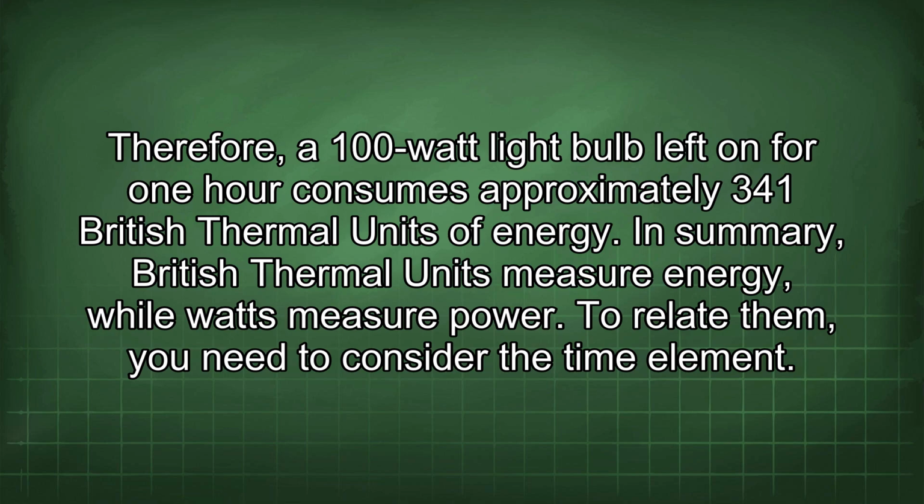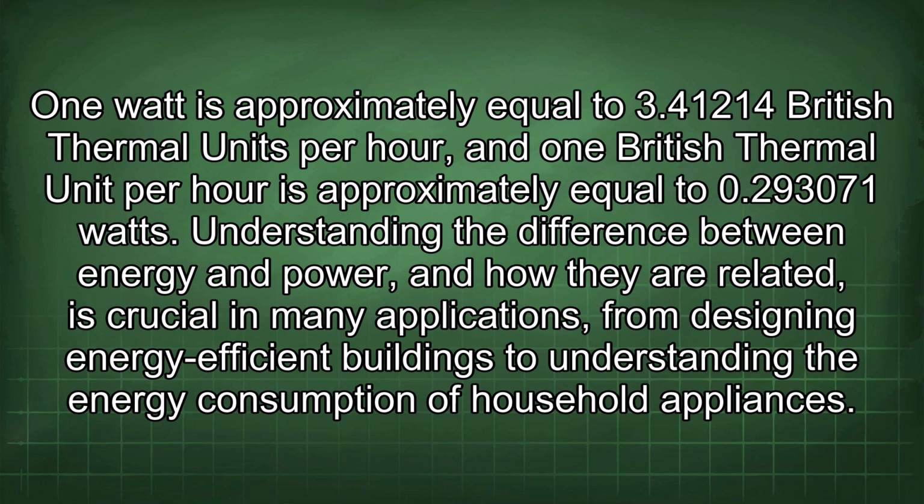In summary, British thermal units measure energy, while watts measure power. To relate them, you need to consider the time element. 1 watt is approximately equal to 3.41214 British thermal units per hour, and 1 British thermal unit per hour is approximately equal to 0.293071 watts. Understanding the difference between energy and power, and how they are related, is crucial in many applications, from